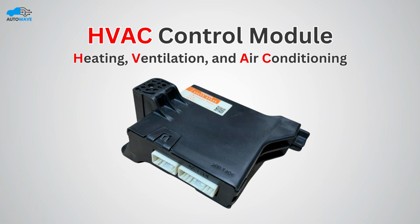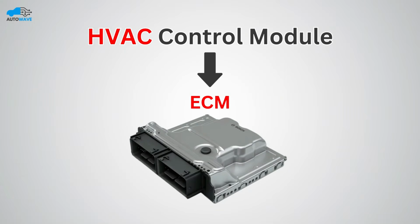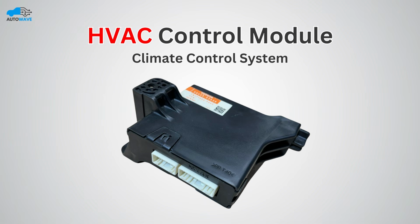Its job is to control and adjust the cabin temperature, airflow direction, blower speed, AC compressor, air mix doors, air recirculation, and defrost functions. In some cars, the air conditioning system is directly controlled through the ECM, while in advanced systems like climate control, a separate ECU is mostly used.